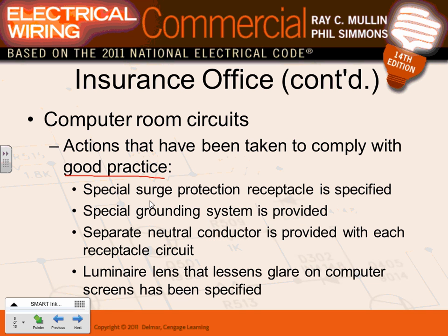Good practice. Number 1, you need to have surge protection. Anybody know what surge protection is in a computer room? You have servers there. You don't want to burn them. Expensive. Number 2, grounding system. You have to have a good grounding system because you don't want to burn your server. Number 3, a different neutral. Why do you think they pull an extra neutral in a computer room where the servers are? We pull an extra neutral because of harmonics. You guys are familiar with that one.